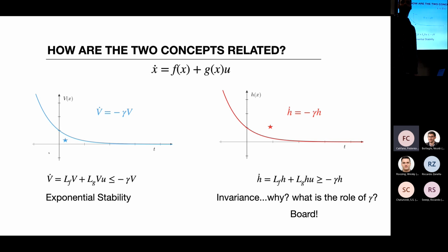You put a lot of bubbles, you sum them, and you have something that is positive. It's like I define a potential field. Yeah, it's like a Gaussian. You could use a Gaussian, right? There is a paper that shows the CBFs generalize the potential field method. For every potential field, there is a corresponding CBF.